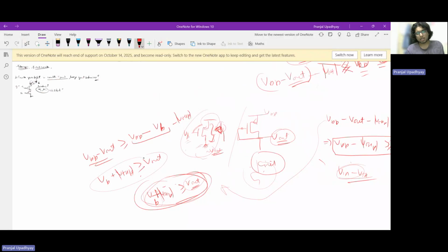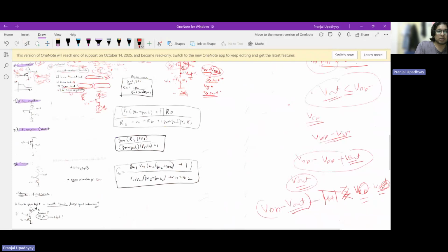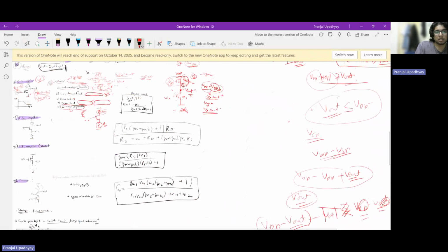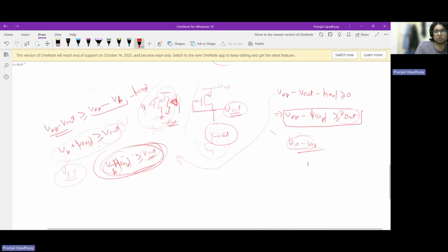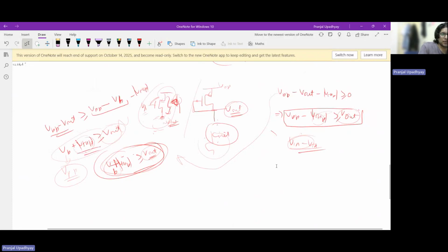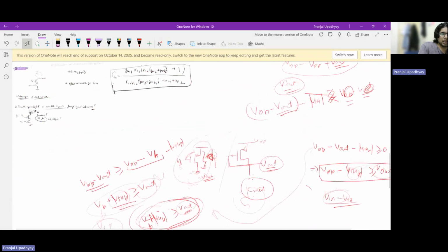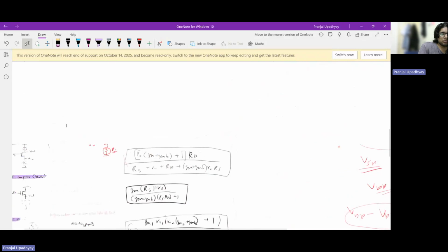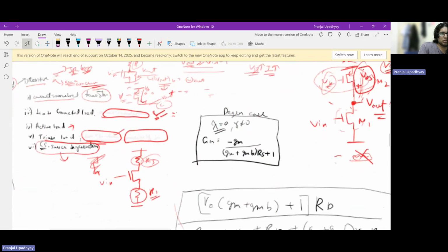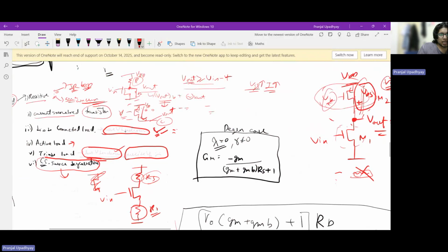And so you can understand that here, if VB is VDD for the time being, Vout can actually swing a bit more in this case as compared to the diode connected load. Thus the diode connected load does suffer from swing limits, because here it is reducing by this term and here it is increasing by this term, up to what extent the output can fundamentally swing. Great, cool. So that being out of the way, we are now able to appreciate that for VB equal to VDD, the diode connected device has some voltage headroom issue, and this one does not.